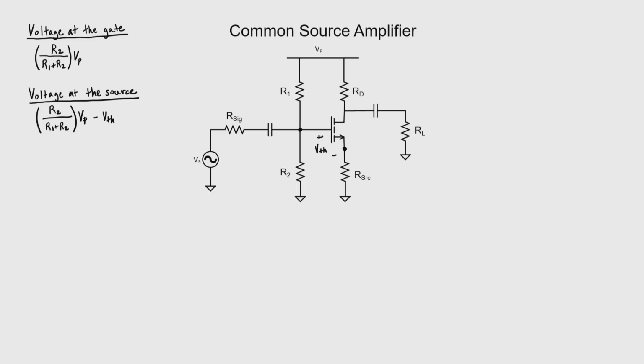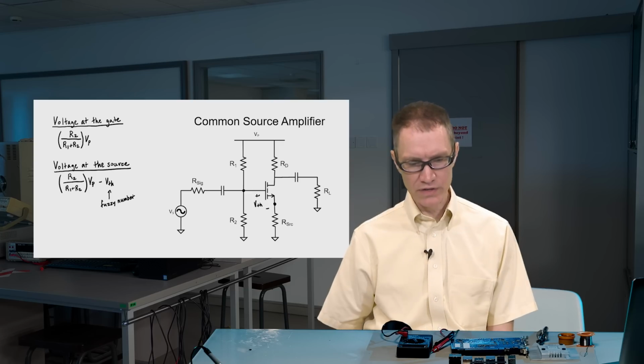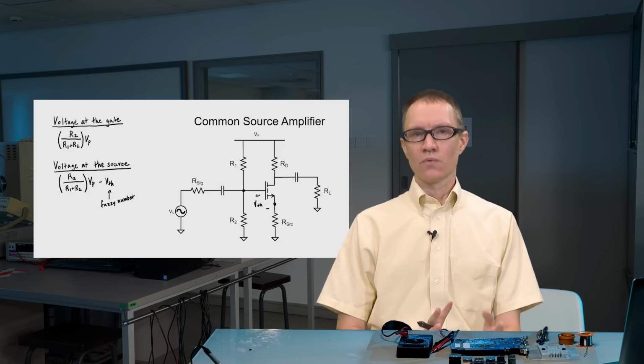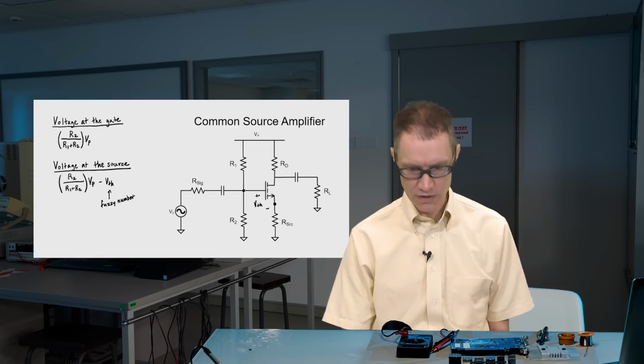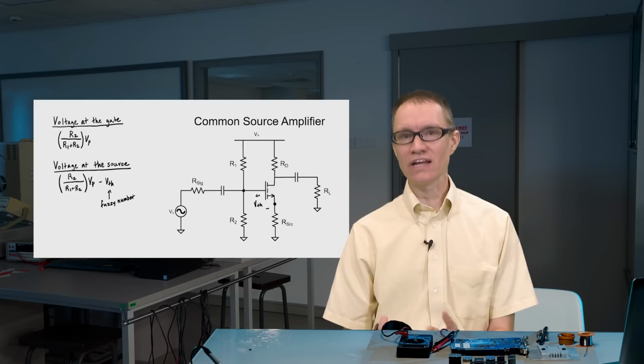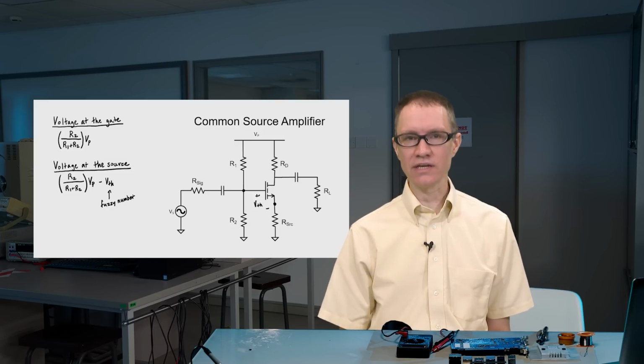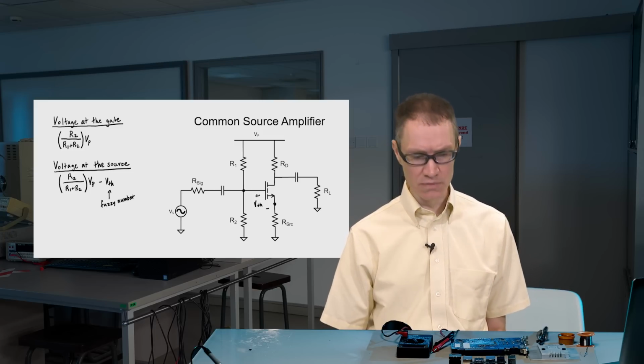The threshold voltage is different for every transistor, and even if you have the same transistor type, from component to component, you might have different threshold voltages. So we could call the threshold voltage a bit of a fuzzy number. Quite often in circuit design, we're not sure what that threshold is going to be exactly, so we have to make sure that our circuit can accommodate a range of threshold voltages. Fortunately, it doesn't make a big difference for the gain, as you'll see in a moment.